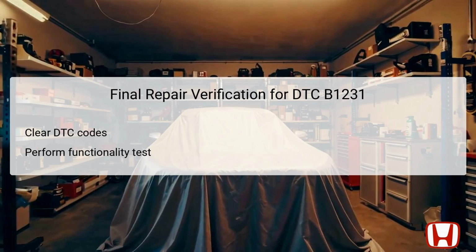This begins with clearing the stored DTC codes from the vehicle's computer, allowing the system to reset. After clearing the codes, conducting a functionality test of the climate control system is integral to ensure that all components are now operating correctly. The technician will monitor the sensor readings as the system operates under various conditions, verifying stability and accuracy. This verification process helps to confirm that the issue has been addressed and that the climate control system is functioning optimally without illumination of the warning indicator. Affirmative results from these tests instill confidence in the efficacy of the repairs conducted on the evaporator temperature sensor circuit.